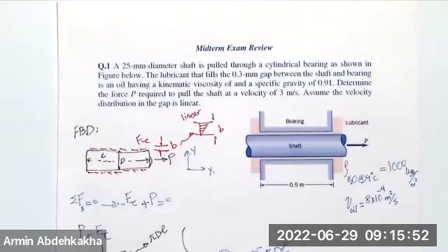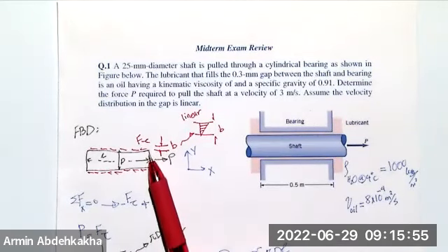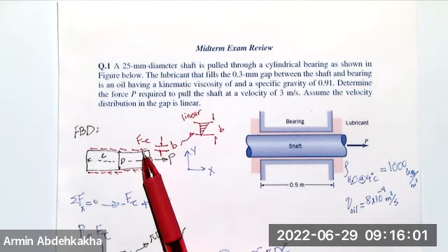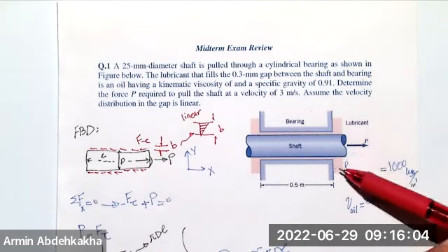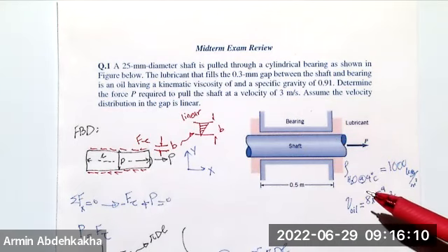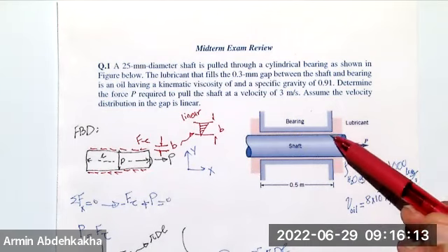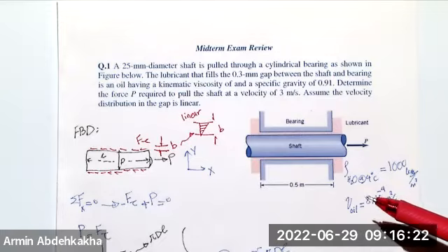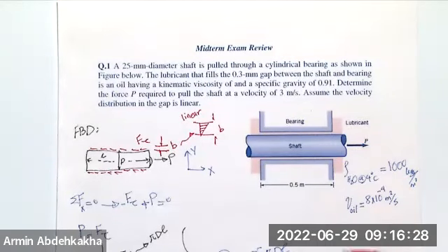Okay, so first you have to know where is the area that tau happens, right? So if that's a circular shape, then whenever you have gap B, you will have tau. So in all over this surface, the bearing is all like a circular shape. Oh, okay, that makes a lot more sense. Thank you. You're welcome. It's circumference times length. If you think of it as circumference times length, it makes it a little bit easier to think about.